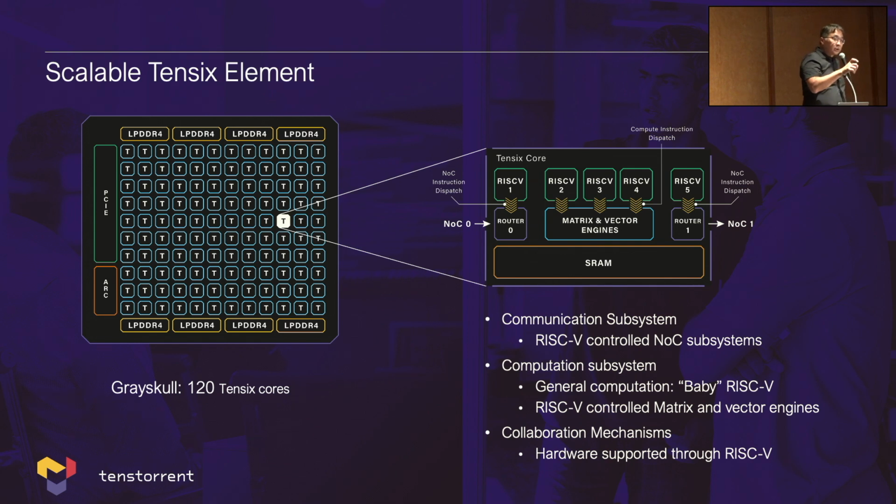And in the middle, there are 3 RISC-V processors used for driving the computation. So they are forming a kind of 2 disjoint systems. One uses RISC-V to control the data movement for the computation. Once the data is moved to the local memory, you use the computation RISC-V processors to perform the computation kernel, and then return the data through the right-hand side of that picture, which is used for sending the data to the destination.